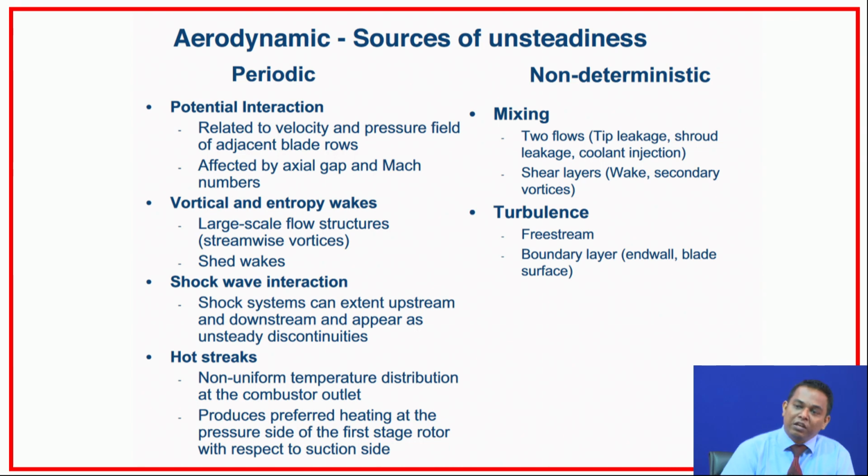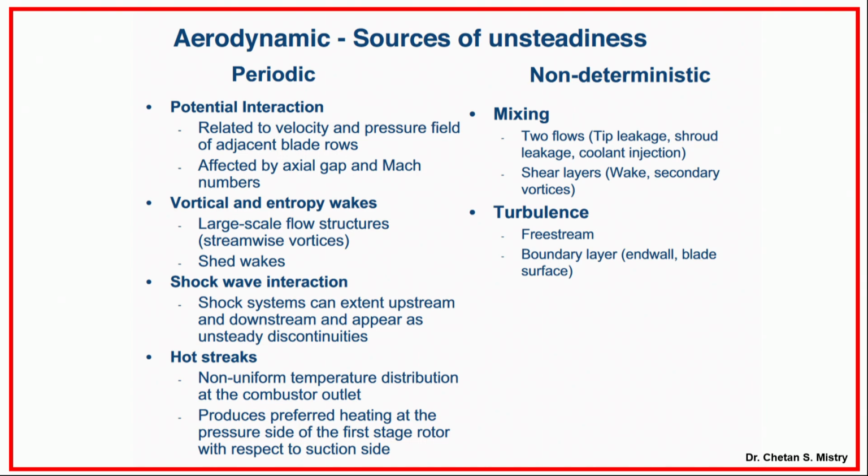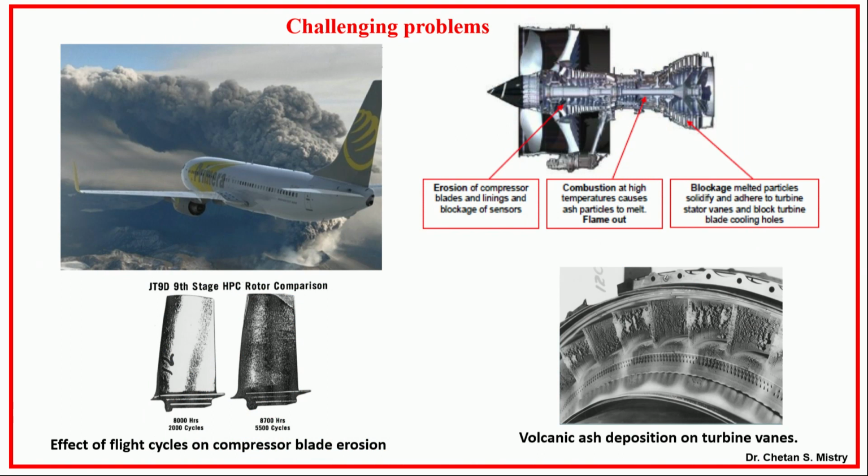Especially if you look at aerodynamics and unsteady aerodynamics, the features in a turbine are much more complex. Because of the shock structure near the trailing edge, and the way in which my flow is behaving between rotor and stator based on my number of blades and number of vanes, the whole physics is changing. And this is what we have discussed. This is the challenging part.